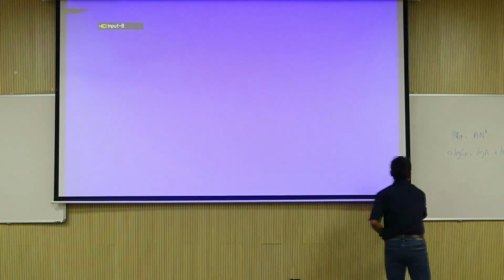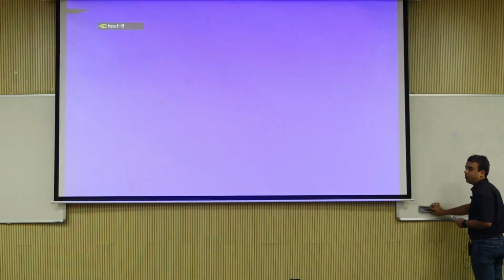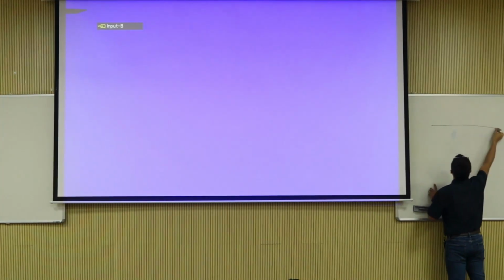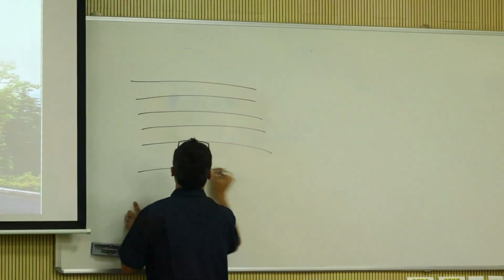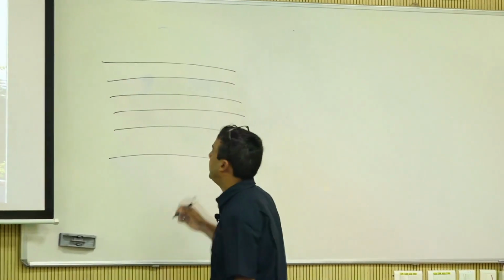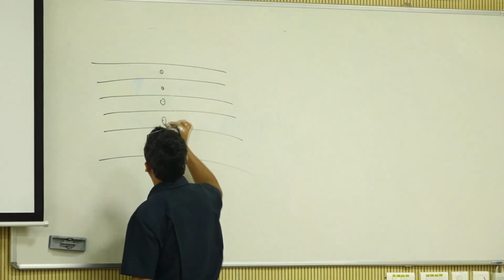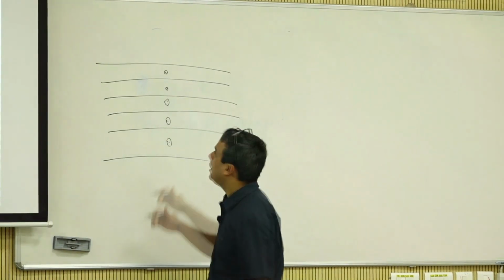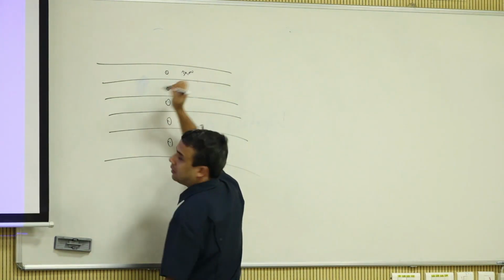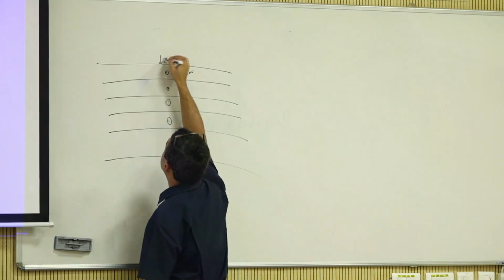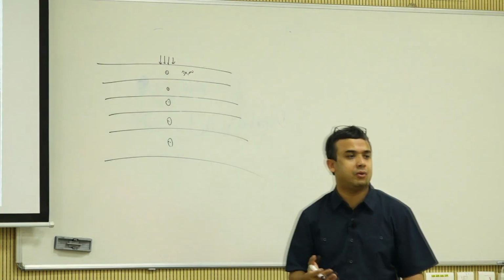So last thing I will say, we said this a little bit yesterday, but you are like, okay, now I have sublayered, I have this layer, I'm going to sublayer this. And you are saying, okay, how am I going to now assign modulus values for all of them? What I would say is, let's just say to start with, assign a value of say 30,000, right? And then apply a load, run your layered elastic analysis, run your IIT PAVE or whatever you're trying to do.